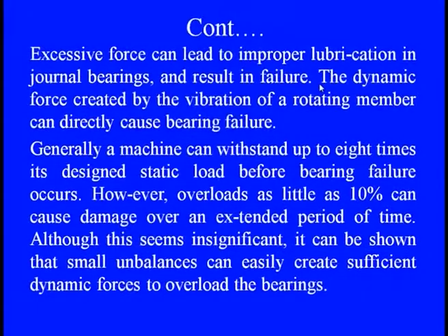Generally, a machine can withstand up to 8 times the designed static value before bearing failure occurs. So, we need to check the kind of forces being generated during rotational or oscillating motion. Also, sometimes even small unbalances can create huge dynamic forces, and these are transmitted quickly because of robust connections, even overloading the bearings, gears or the shaft.